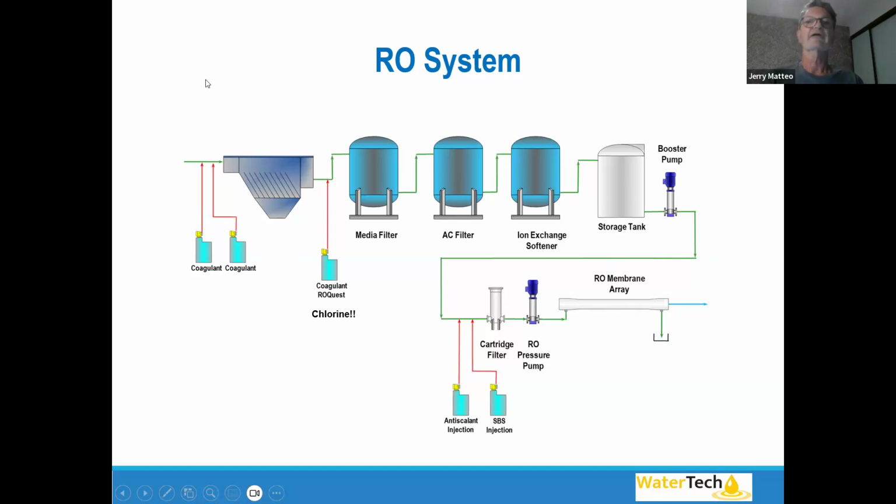So I put a clarifier here because that is one way we can remove suspended solids. Probably most of you, since we're talking to a lot of wastewater people, are familiar with clarifiers. This is just a laminar plate clarifier. I'm going to show you a photo of a big plant in Trinidad that uses a clarifier like that. Most don't, but you can. Media is the most common way to remove particles.